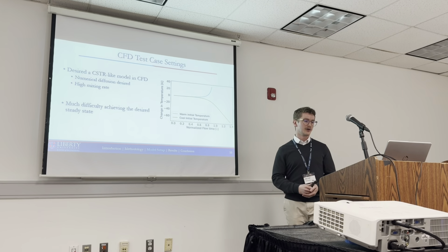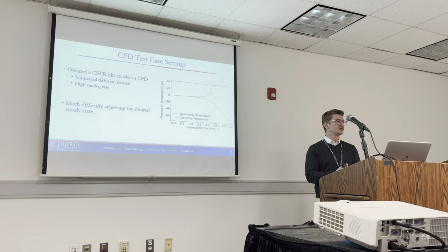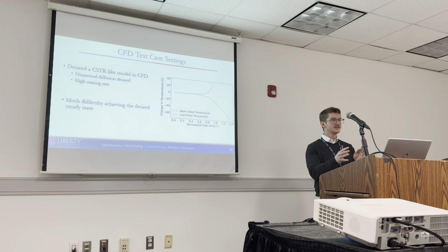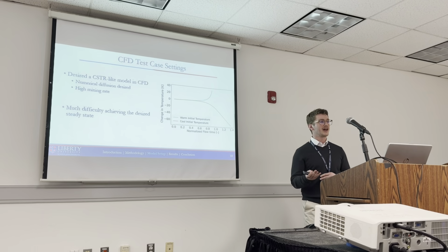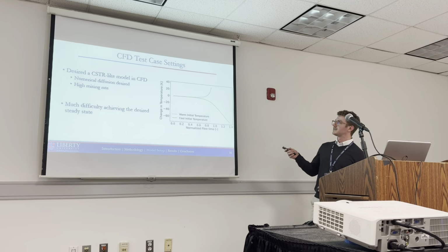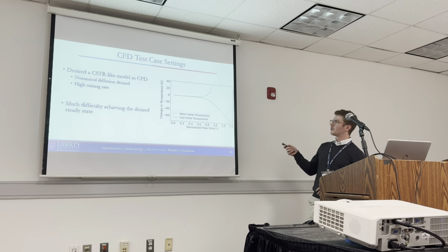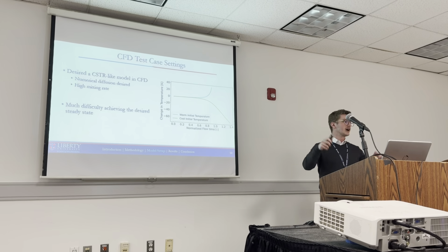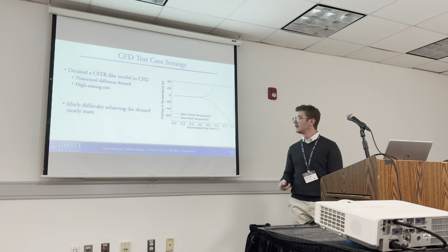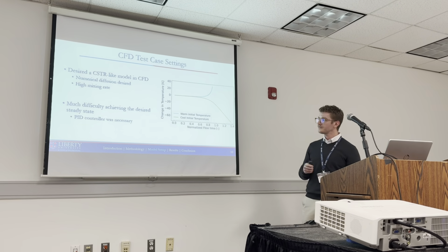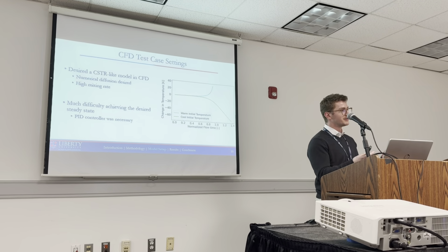but it was actually very difficult to get a steady result with this model, as can be seen in this image here, where we have CSTR temperature, change in temperature from its initial conditions for the exact same cases, with the only difference being the initial temperature, which only differed by 1/100th of a Kelvin. And we see that there are vastly different responses, where the warm initial temperature case exhibited thermal runaway and just went to thousands of degrees Kelvin. The other one didn't react enough to sustain that temperature and just fell off to the inlet temperature. And so we found that a PID controller was necessary in order to obtain a result with this CSTR model.